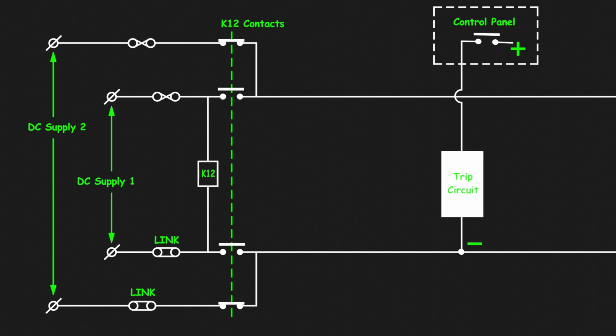Some manufacturers provide fuses at both connections of the auxiliary contactor, 1 fuse here, another fuse there. This is because if, for any reason, this coil gets shorted, then either of these fuses will blow and save the rest of the circuit from the effects of the coil's short circuit. This is considered a good practice.